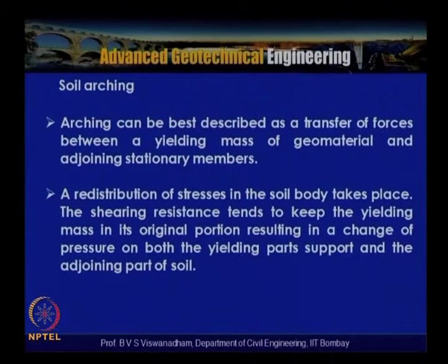So let us now try to understand soil arching. Soil arching can be best described as a transfer of forces between a yielding mass of soil and adjoining stationary members. Stationary members are nothing but the non-yielding zones. In the case of buried conduits, it is the side walls.